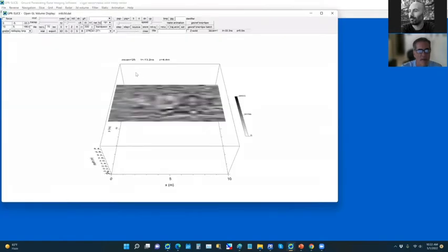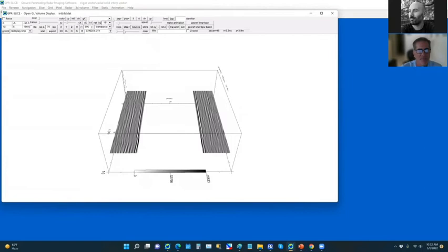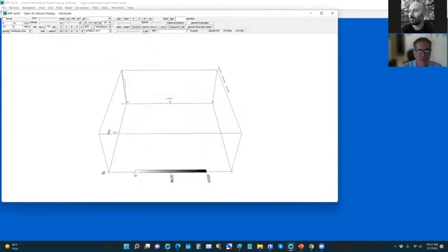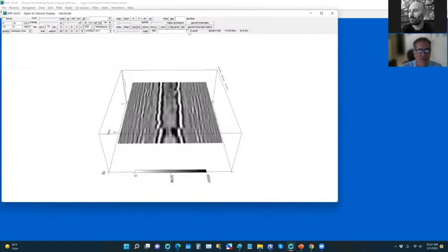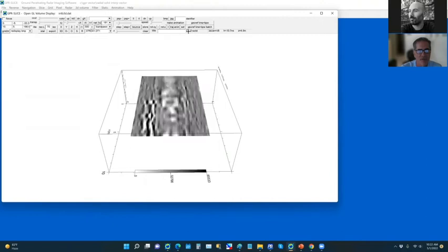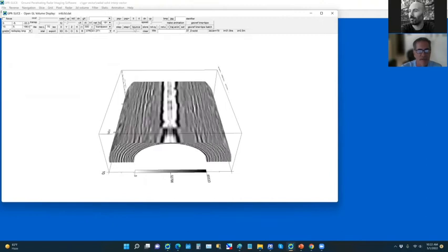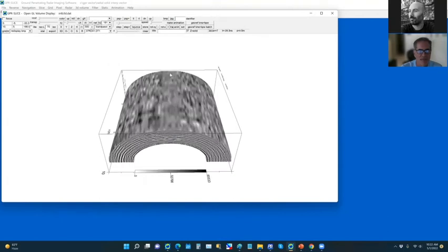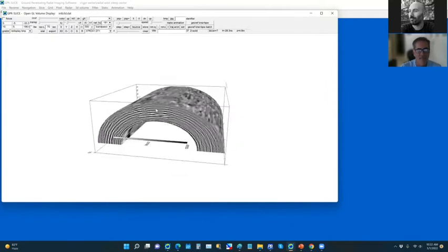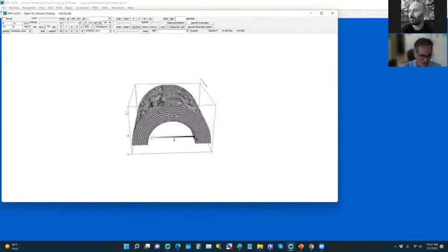And here's a solid cone or a half cylinder of data. We'll just put this on solid here in a second, and it'll fill up completely here. This was data that was collected with radargrams that were only made at about 0.5 meter on this radial site. And then we interpolated them maybe 30 times and then compiled all that data into a 3D volume. So that's also available for you as well.